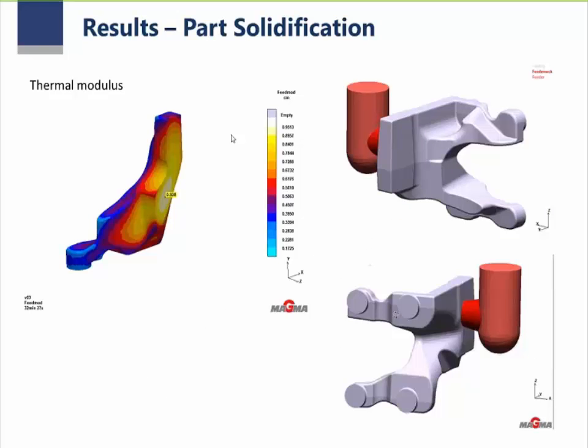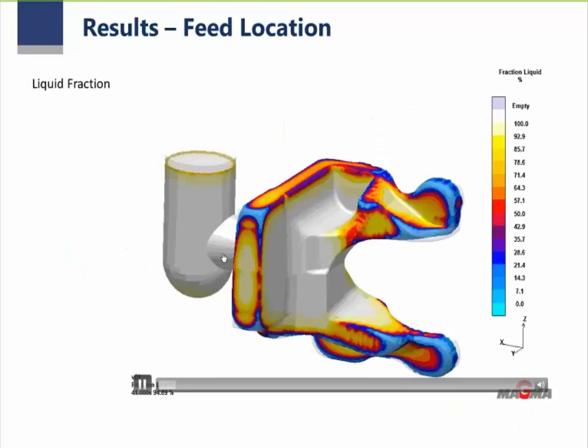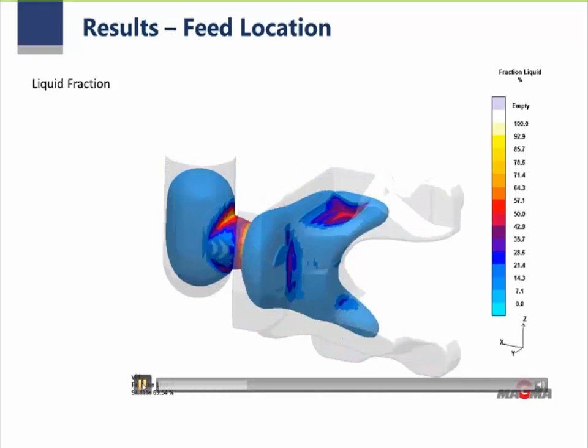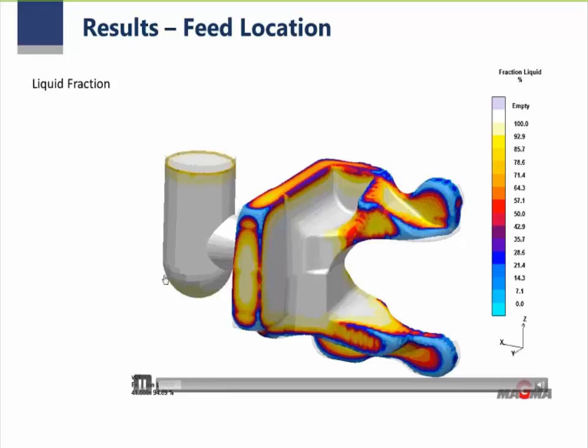And because of this, when you are trying to get this process from the manufacturer, you see that it makes sense to add close to this region a kind of feeder, which will also help with this condition. So if you go to the next slide, here using the feeder, you see that now it's much better, and the last part of solidification is now inside the feeder.